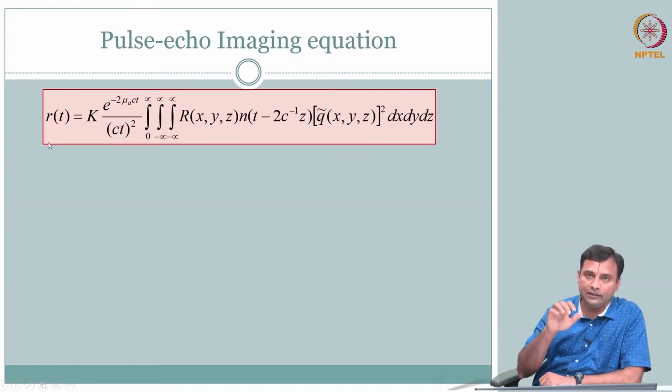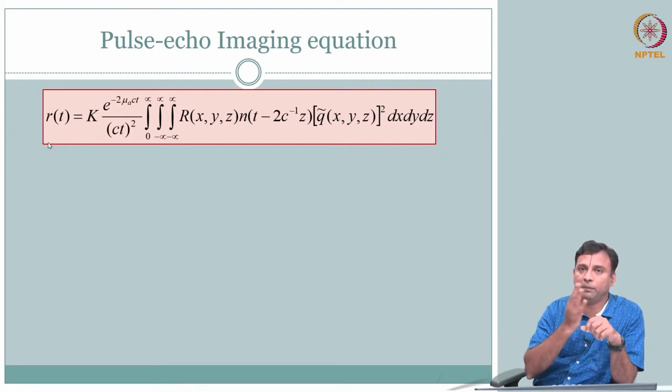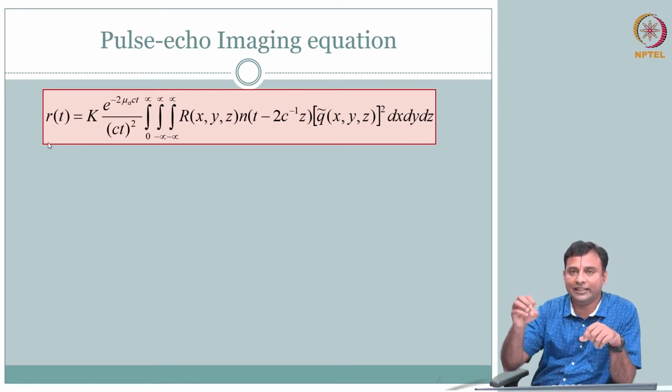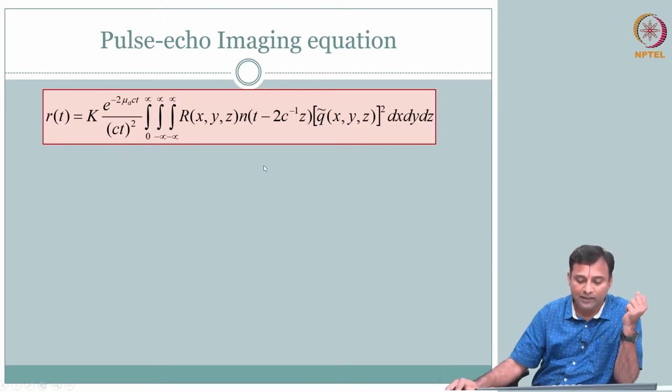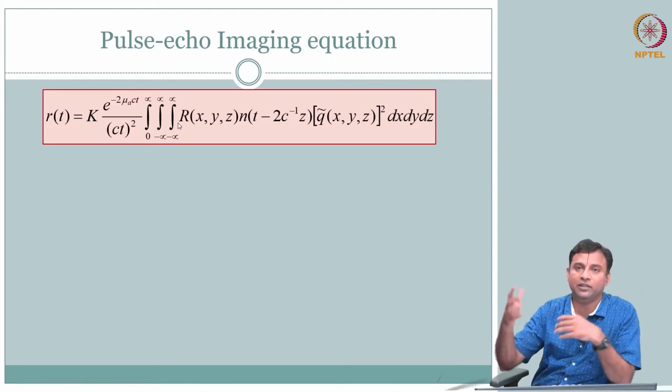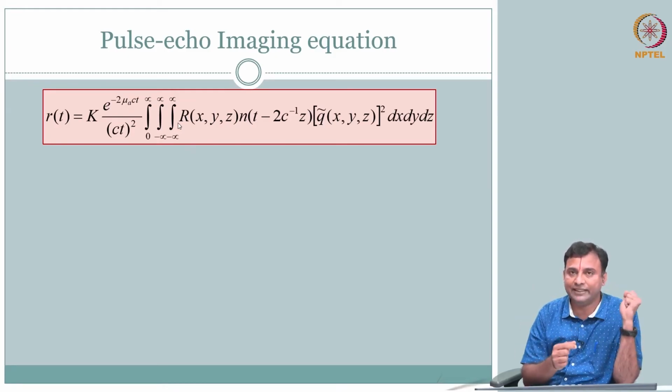So you send a pulse, that pulse goes, there is a point source, so the plane wave goes, it gets hit, scattered signal PS comes back, and the amount that comes back is depending on the reflection coefficient, and then we said superposition theorem, and then you come and hit on the surface, and then we had everything added on the surface, whatever falls across the face is added. So we get our received signal as a function of t.